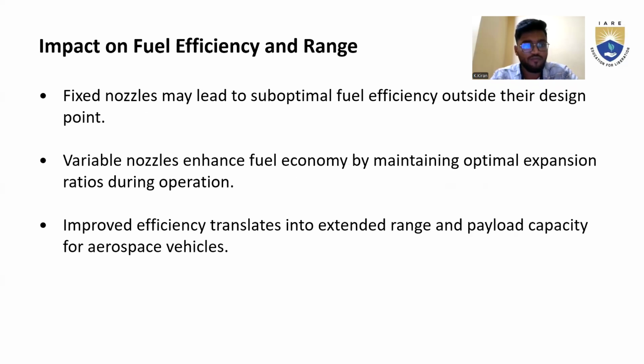Impact on fuel efficiency and range. Fixed nozzles may lead to suboptimal fuel efficiency outside their design point. Variable nozzles enhance fuel economy by maintaining optimal expansion ratios during operation. Improved efficiency translates into extended range and payload capacity for aerospace vehicles.